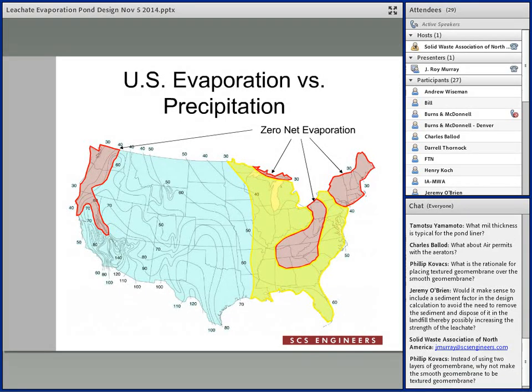If you wanted to use just a single geomembrane, we use 2 layers of geomembrane. The second geomembrane is technically our protective cover. Going with just a single geomembrane, you're much more likely to have an event where something falls on it and maybe pokes a hole in there and maybe you don't know about it.